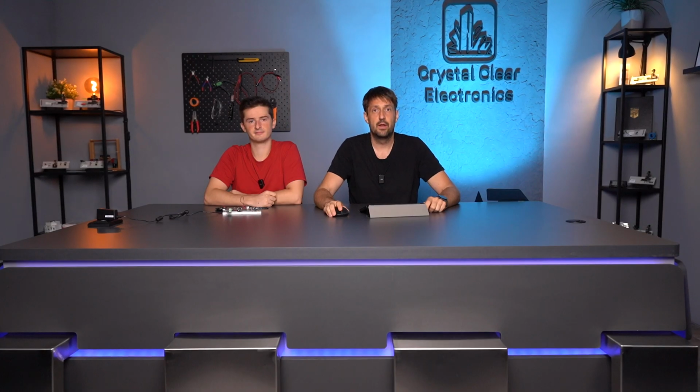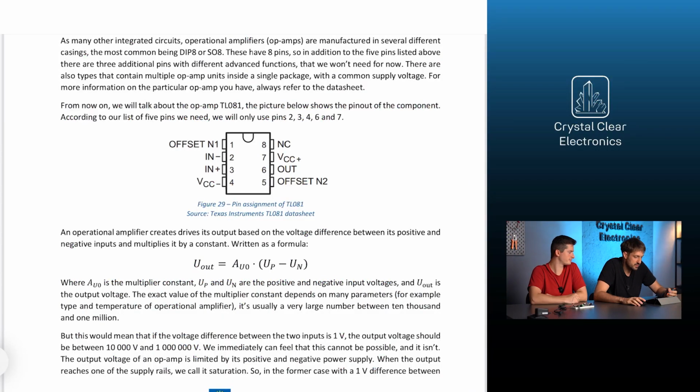But before that, we must first understand how operational amplifiers work, and we need to learn some new terms. Operational amplifiers are manufactured in different types of packages. The most common packages are the DIP-8 and SO8, which have 8 pins. Some types contain several op-amp units inside a single package. In this case, they share a common supply voltage. From now on, we will talk about the TL081 op-amp. Its pinout can be seen on the figure.